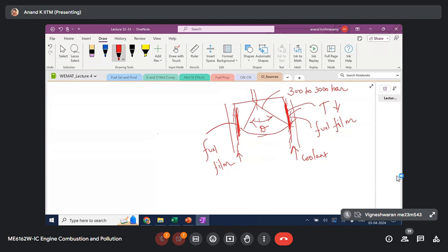It will increase, sir. The HC will increase. HC will increase. We already discussed the mechanism of fuel vaporization and mixing. If you recollect, in the very first chapter, the mechanism should be something like this. When the fuel is sprayed, the outer periphery will be broken. It will be like a film initially. Because of air resistance, the film is broken. The air is offering shear force. Due to the shear force, the outer periphery of the fuel spray will start to break and form drops. So the drop formation has to take place. Without drop formation, vaporization is very difficult.